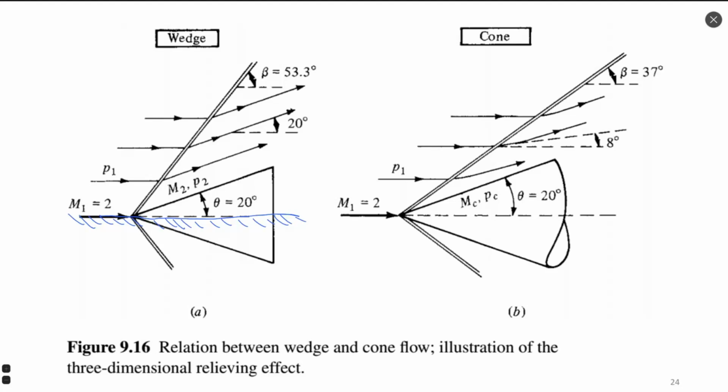Calculation in such a case is known, right? We can provide such computation. We need to use the Mach number before the flow changes and the theta angle of the body. Then we use the theta-beta-M relation. We find the angle of the body. You can see it in our diagram.